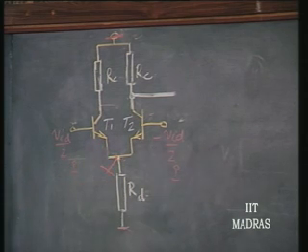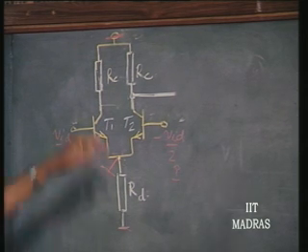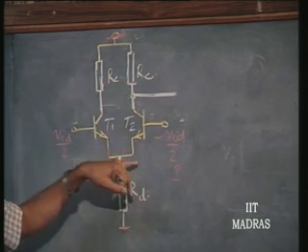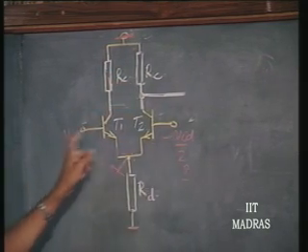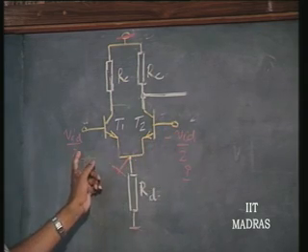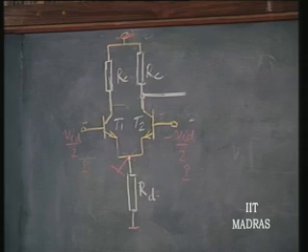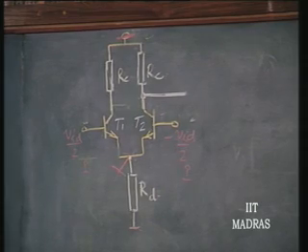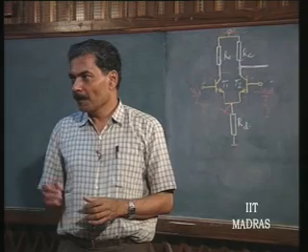RE itself is going to be governed by I naught by 2, okay. RC by RE here and RC by RE here, okay. The phase shift is because of the assumed shifting of this here. This will be out of phase with this by 180 degrees, that is the signal we have assumed, okay. So, this is the analysis that you can adopt for differential mode.